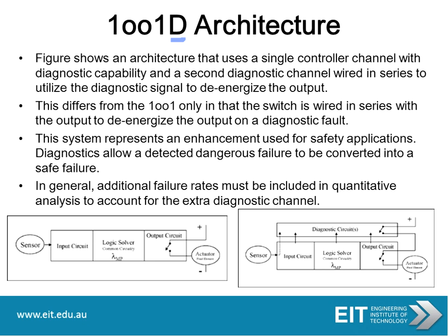Now the 1oo1D architecture, so we've got a single controller channel with diagnostics capability and a second diagnostic channel wired in series to utilize the diagnostic signal to de-energize the output. So on the left hand side we've got the previous one, and now we've added diagnostic circuits, the D that you see added to the 1oo1 architecture. So it differs from the 1oo1 only in that the switch is wired in series with the output to de-energize the output.